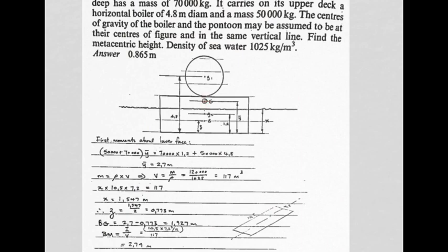Then from Archimedes' Principle, it follows that 117 cubic meters of water must be displaced if we have that much mass of vessel. In other words, if the displacement of the vessel is that much mass. Okay, so next is to find the draft, and because this is a vertical sided, very simplistic rectangular pontoon, we can work out that the draft x multiplied by 10.5, which is the length, times the width, equals the volume displaced. So 1.547 meters is the draft of the vessel, how much it sticks into the water.